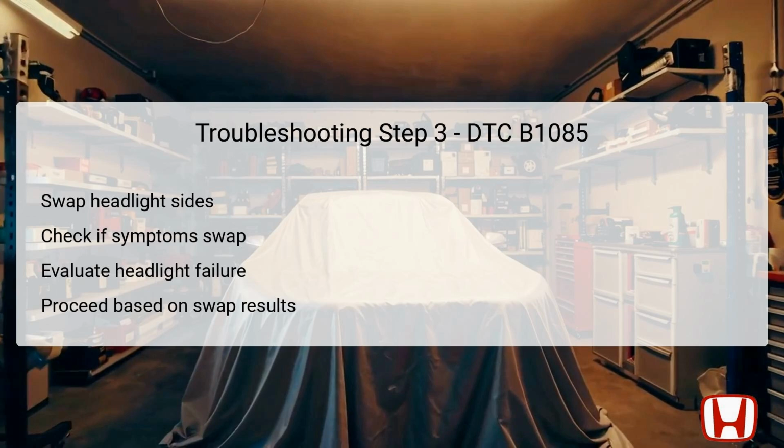In contrast, if the symptoms do not change, the technician will need to explore other hypotheses about the failure, particularly inspecting the wiring or relay components linked to the headlights.